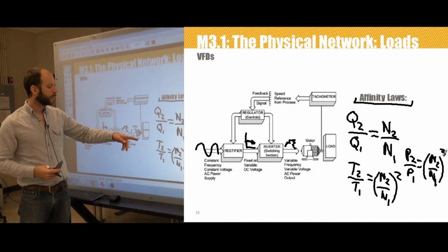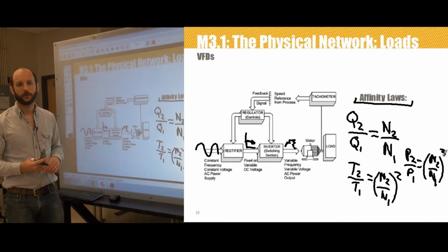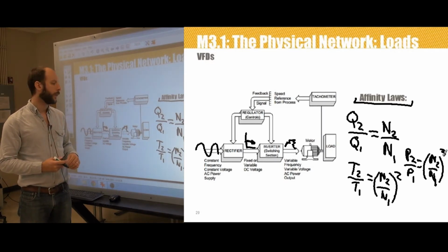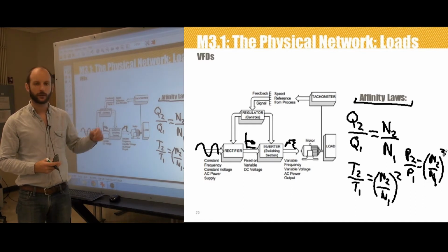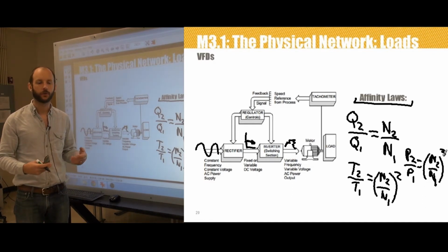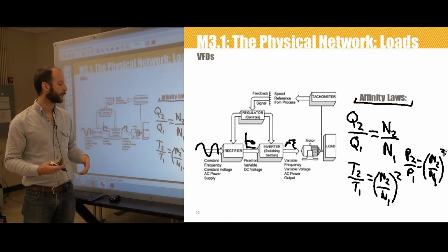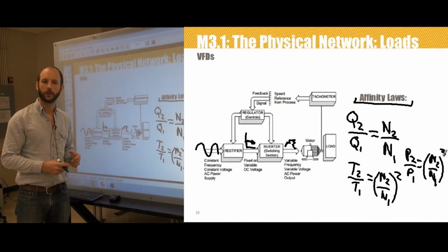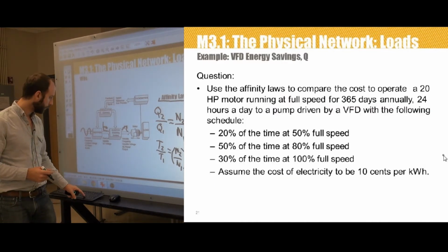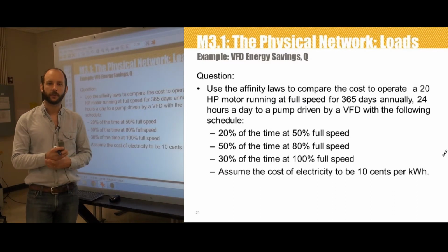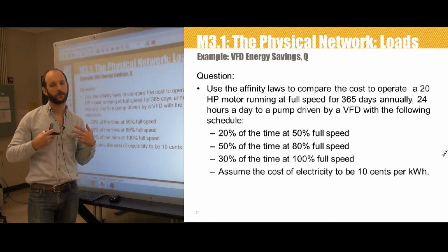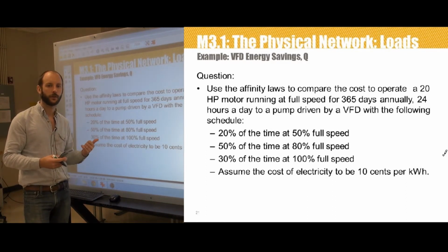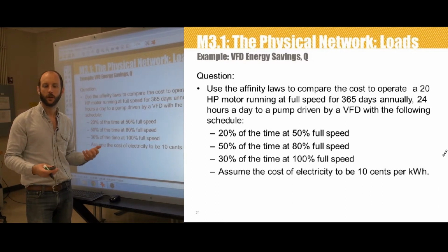In addition to the use of a variable frequency drive for energy efficiency, VFDs are often becoming more common because you could integrate them with a sensor and put them into some sort of feedback control system, building management system in manufacturing processes. So VFDs in a process control application is another thing that you might see these in. So the use of VFDs to save money on electric bills is probably the most typical application that you'll come across. And so let's perform an example to see how this is achieved using the affinity laws.